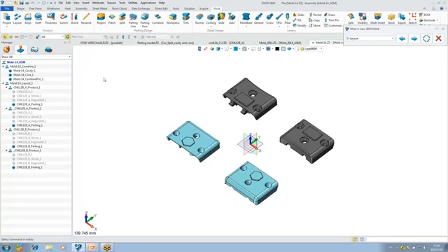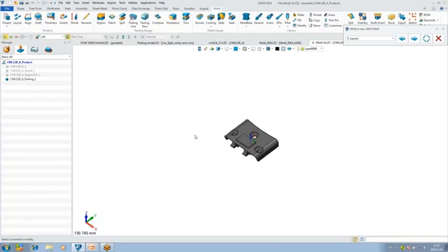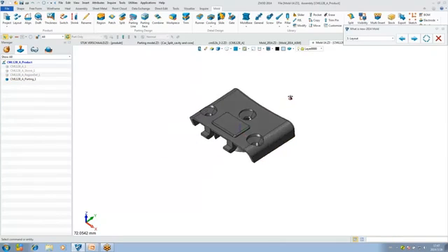What's more, if you want to do the parting for a different product, right here we have 2 product models in this small project. If we want to go into the specific product model to do the parting process, we can use the switch command. It will show all the product objects in the list, so you can click it and click OK, and you can jump to it to do the parting process.